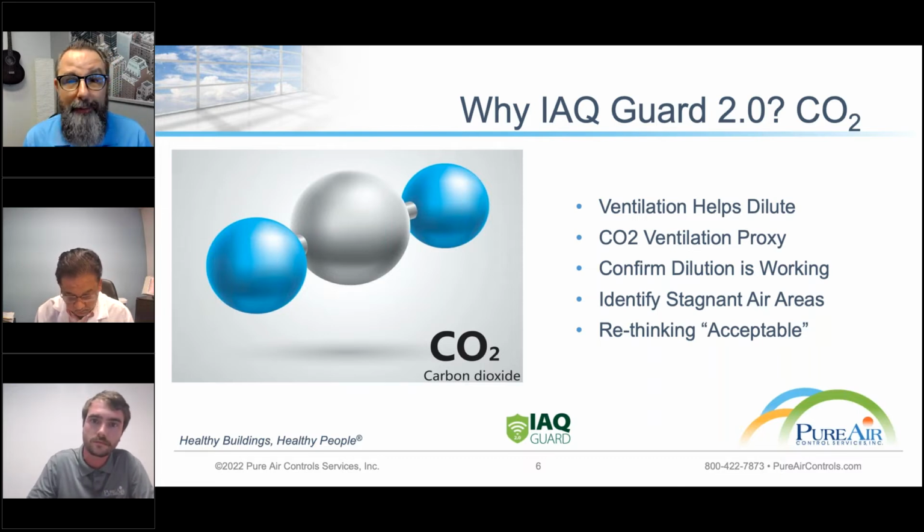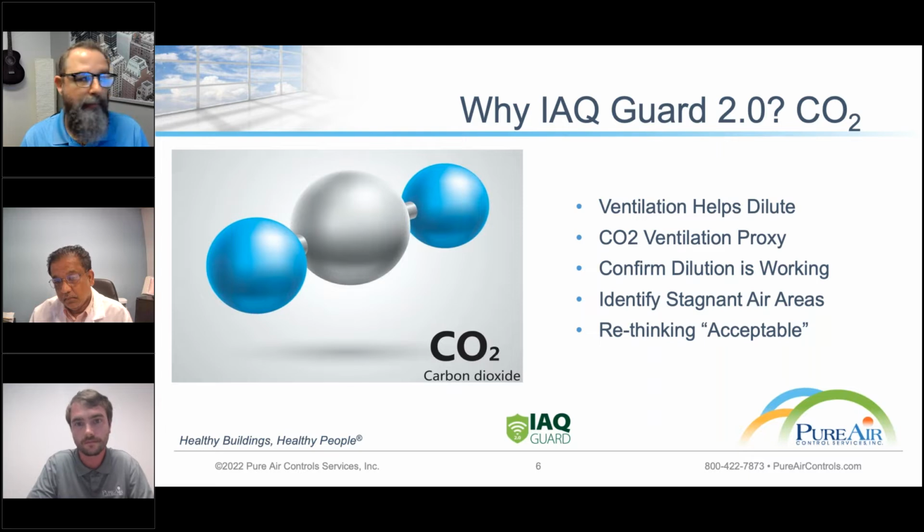If CO2 goes up and stays up even after people leave the building, then in some cases that might indicate that some of the equipment is not working, or the building isn't being flushed properly or as it was designed to. So you can use this type of monitoring platform to confirm that the dilution or building flushing protocols you've put into place are actually working, and doing it in the amount of time that is needed to have it be acceptable.